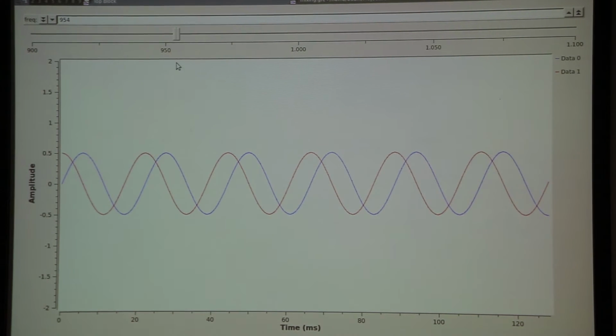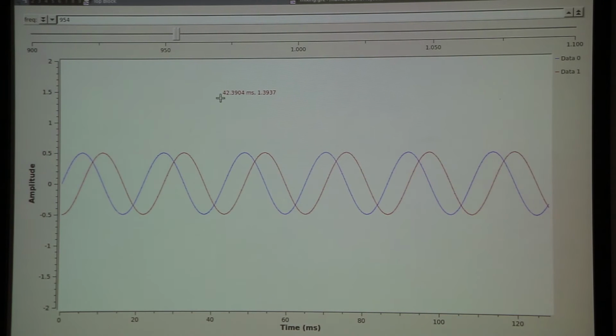If we go to the negative frequencies, they've swapped round. And this is a key to being able to work out what the phase of our signal was and whether it was a positive or negative frequency to begin with. Because we now have these two different measurements, we have a bit more information, and that extra information is what lets us work out the phase of the signal.